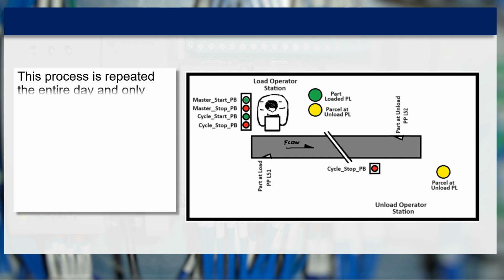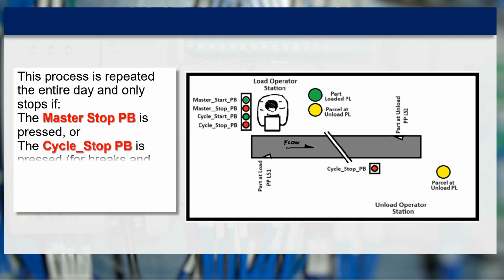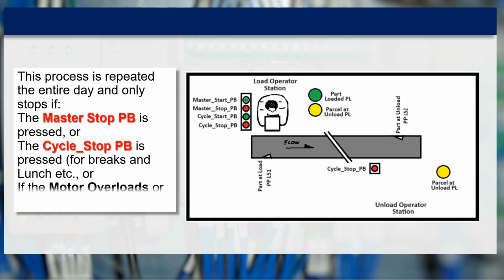This process is repeated the entire day and only stops if the master stop push button is pressed, or the cycle stop push button is pressed for breaks and lunch, etc., or if the motor overloads or overcurrent devices trip.